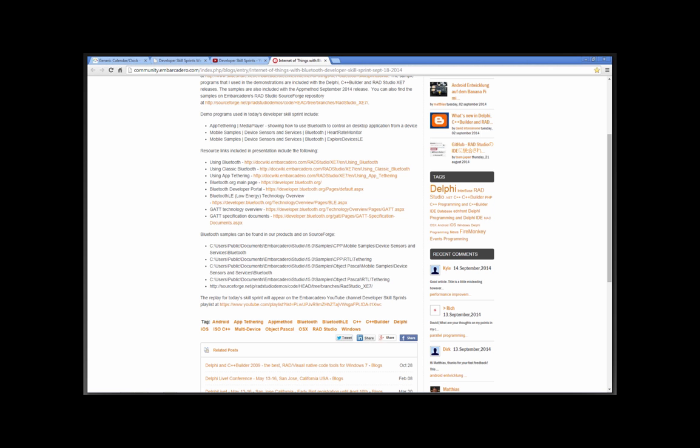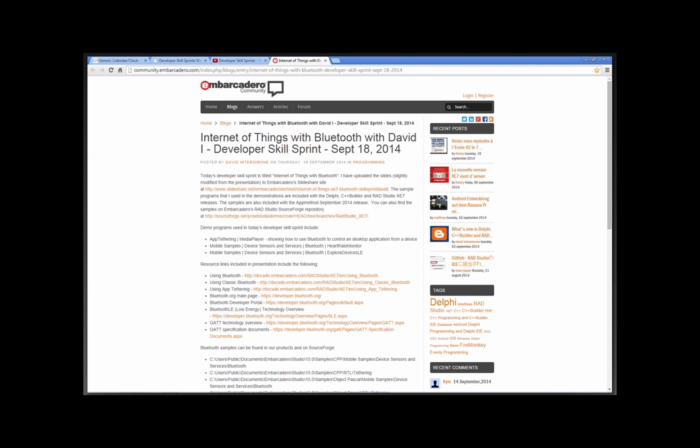So here's a question from James. He says that the Bluetooth UUIDs in code were big, long UUIDs, but the IDs on the website were short 4-digit numbers. Can you explain the relationship between those again? If you look at the UUIDs that are used, the first long word of the GUID or UUID matches the hex code from the Bluetooth standards websites that I link to. So, as I mentioned, 180D for, I think, heart rate monitor.